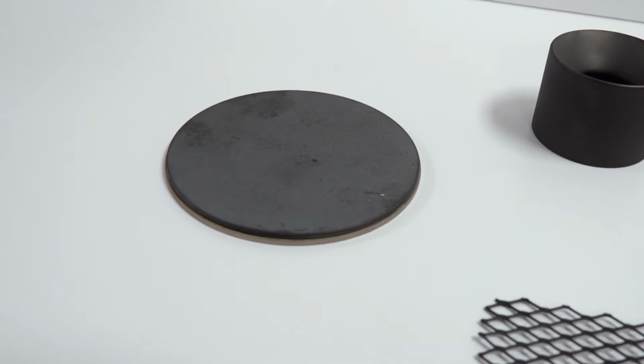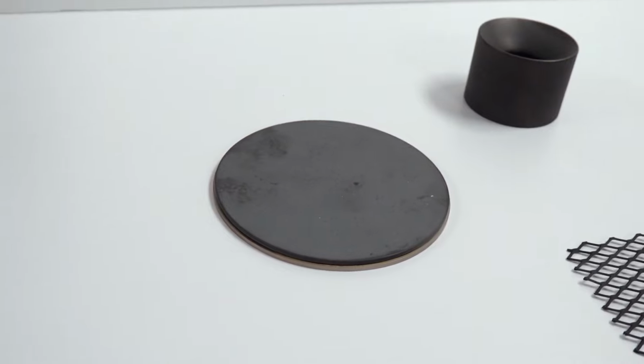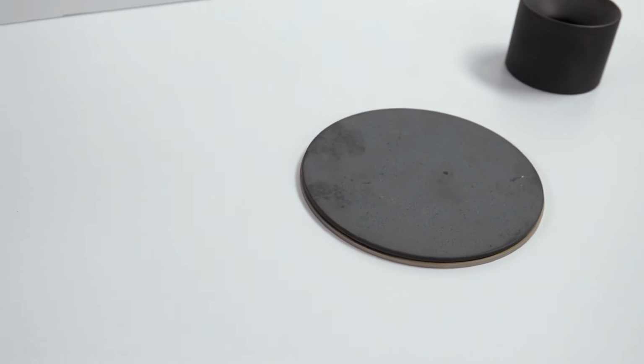So what about this one over here? What's that about? This is known as a CMP pad conditioner. In the semiconductor industry, they will use a CMP process many times when they're building an integrated circuit. It will flatten out the silicon wafer so that they have the exact same device in the center as on the edge and improve their yield. Well, and then all those special characteristics, the toughness, the hardness, is going to make sure that that diamond, that sanding disc stays uniform, so you're not getting a taper or anything. Day after day, it's always the same, reproducible, and meeting the tight specs.